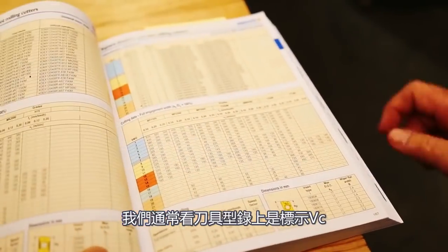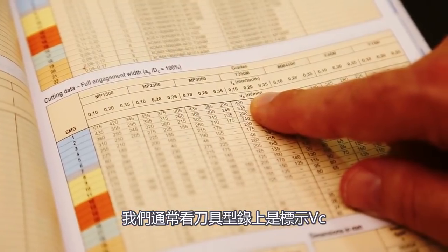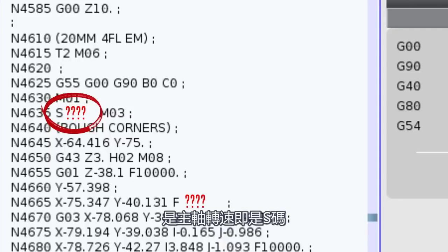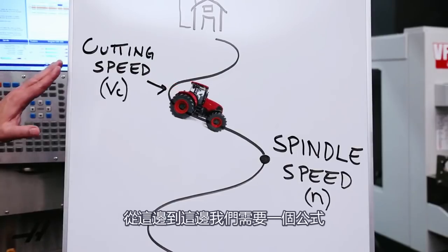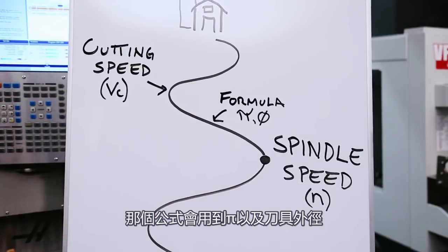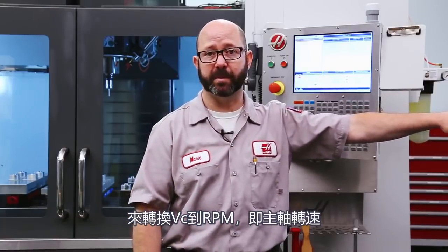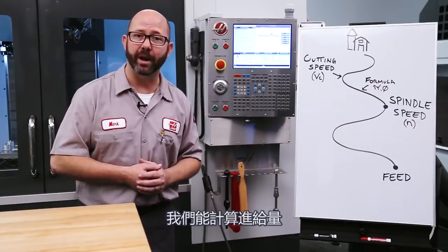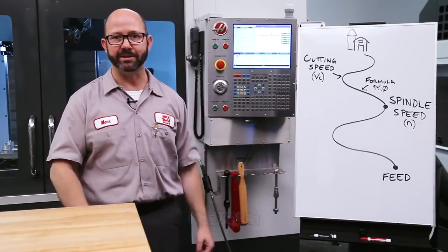We'll get our tool's cutting speed in meters per minute right from our tool catalogs. But to control the Haas machine, it needs an RPM value, a spindle speed. That's our S code. To get from here to here, we're going to use a formula. And that formula is going to make use of pi and our tool's diameter to convert our meters per minute into an RPM value, a spindle speed. Now, once we've got that RPM value, we can calculate our feed rates, speeds and feeds.